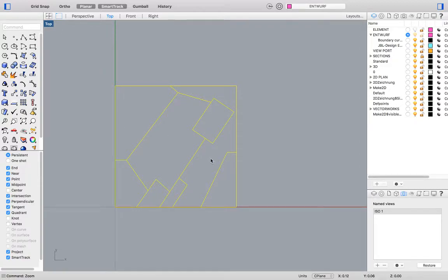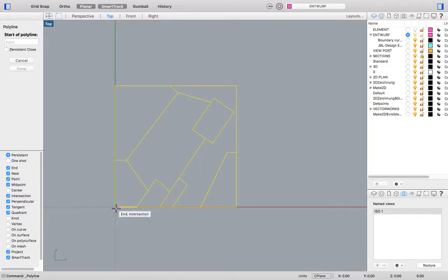And the first thing you'll notice is that actually the model is at the wrong scale. If you look down here, you'll see dimensions. And it's 0.15 meters in length, and we know that we've made this in millimeters, so it's correct in millimeters, but we want to scale this up by 100, so we want to make this line, instead of 150 millimeters, we want to make it 15 meters.